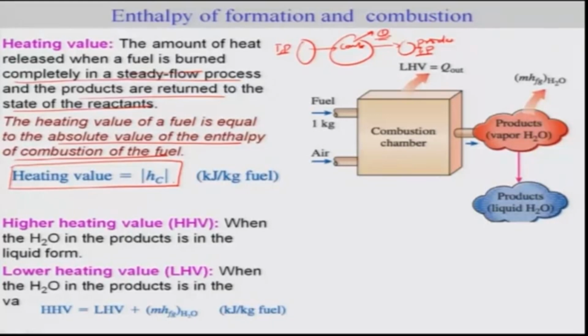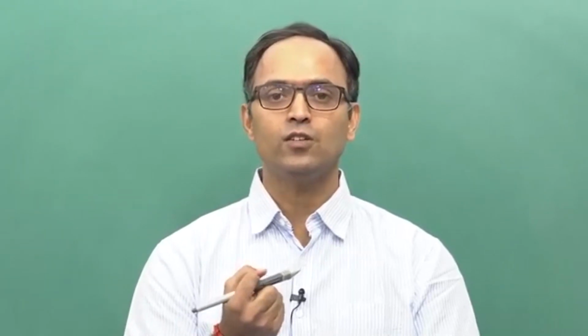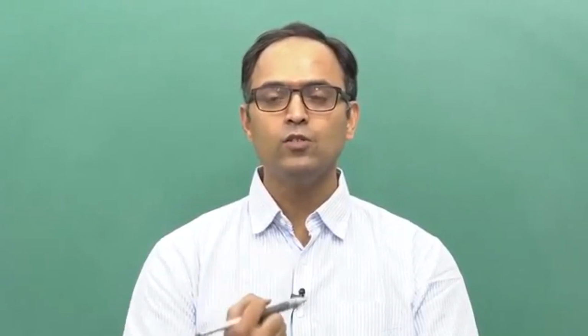Now it depends whether the product is in vapor state or liquid state. Fuel, particularly hydrocarbon fuel, will contain a certain amount of hydrogen, and it will obviously yield water, which can be in a vapor state or a liquid state. If the water in the product is in the vapor state, the water vapor will consume the heat of vaporization energy, or the latent heat, and thus it will reduce the amount of heat released from the combustion chamber.